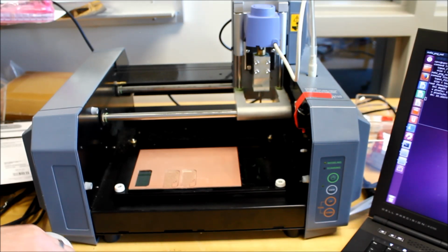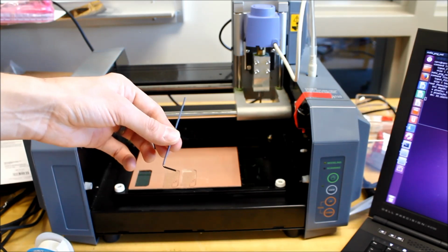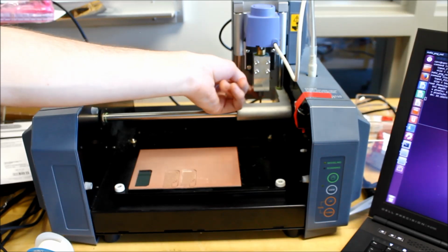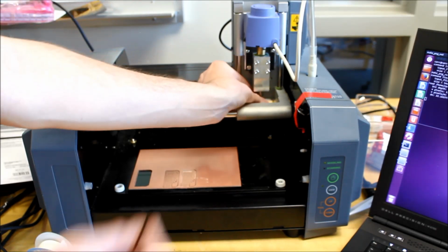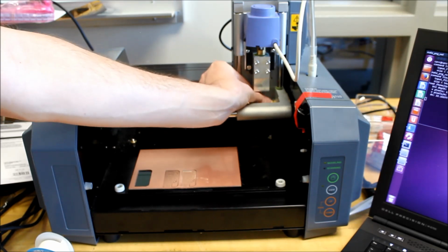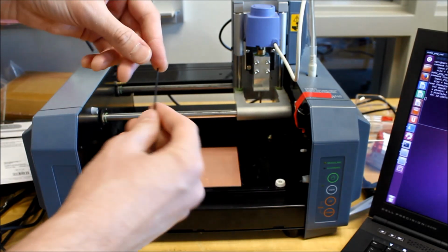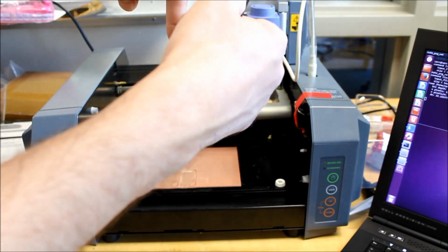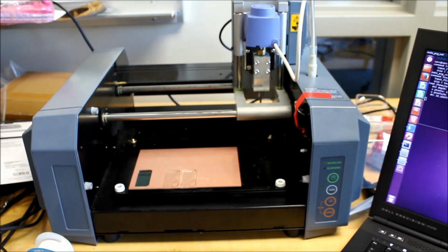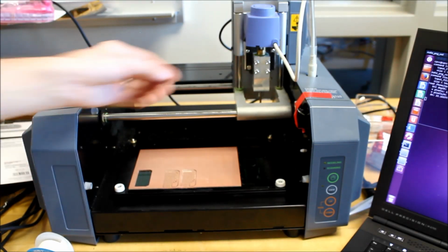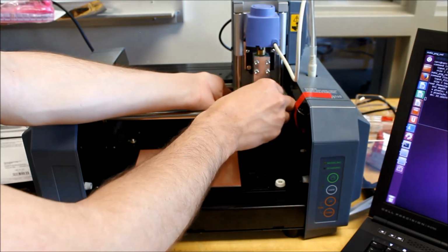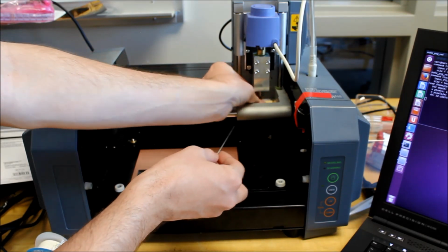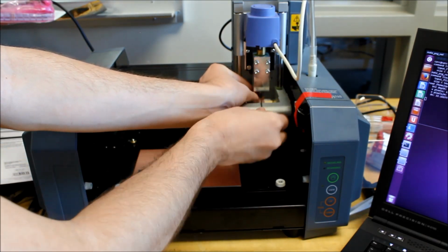So first, find the Allen wrench that you need, and you can spin the spindle manually with your fingers to make sure that the set screw is oriented towards you. Now there's a set screw on either side of the bit. So the bit's here, and there's a screw here and a screw there, or at least a screw hole on both sides in the spindle. There's only one set screw in there. So turn the bit until you find the set screw. So it's not that one, it's the other. And then loosen it